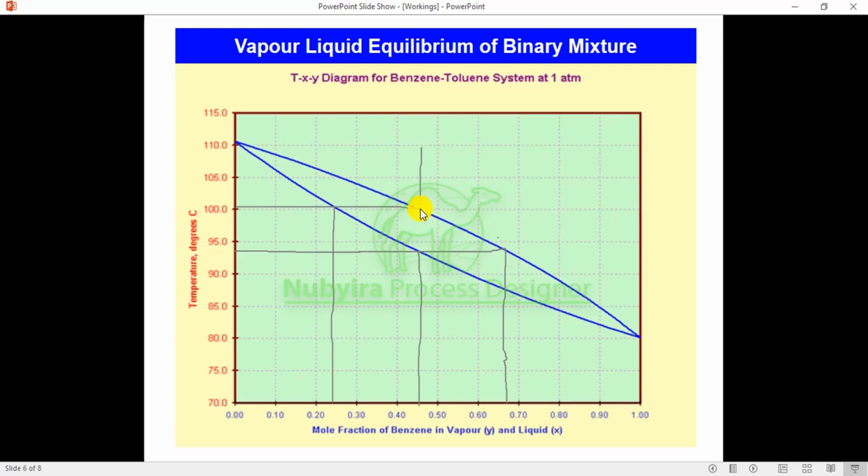That is where the first liquid will drop if you are cooling down from high temperature. But now we are heating from low temperature. So when you heat the mixture to a higher temperature and it reaches the dew point of the mixture, you are going to have the last liquid composition, and this liquid composition will be very low compared to the initial composition for the lighter component, because the heavier components want to stay in the liquid state. So that's the idea of this plot.